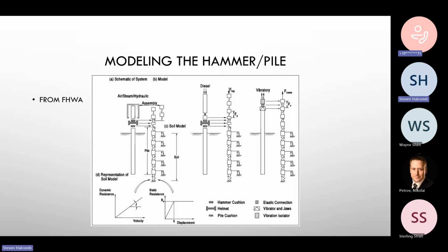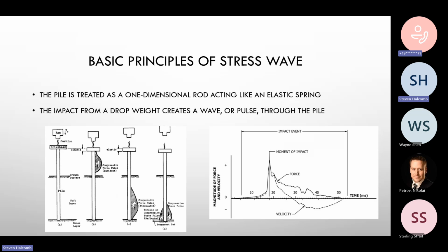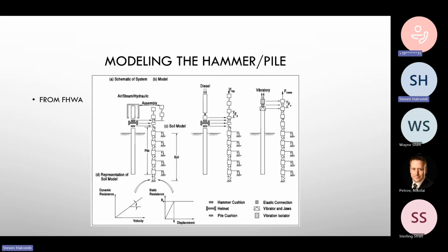We take that wave that I just showed you, which essentially occurs over the length of the pile, and then we can correlate or relate that wave to those individual sections of the pile. That's how we work it, and then we're able to derive soil parameters when we do the signal matching down the road, which we'll talk about. We can then match everything up and get a good quality match between a computed wave and a measured wave. Right now, we're just talking about the measurement, but this shows you a bit of the holistic picture, or one step in the process.